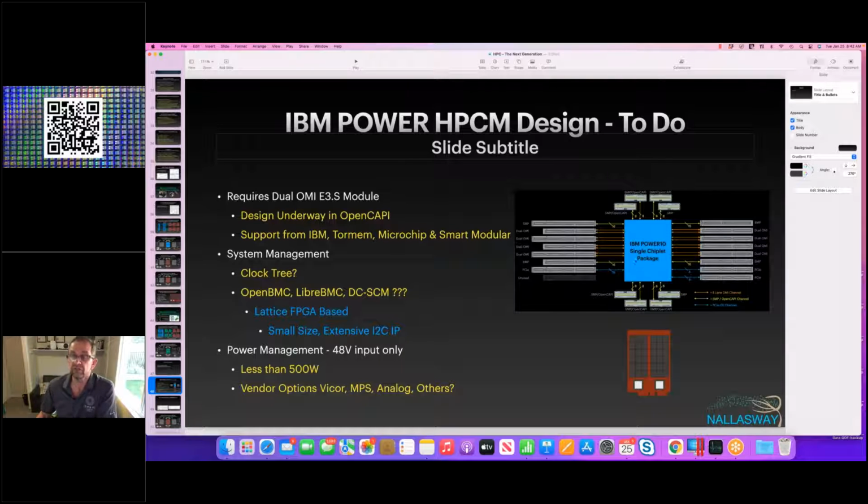Obviously, if you dropped in, let's say, an Intel CPU in here, which maybe has HBM on board and CXL, then all these channels would be CXL, and we just plug in the Samsung CXL module, and we're off to the races. So what I'm doing is, because the open memory interface is already available in a JEDEC differential DIMM format, but that's not compatible with what we're trying to do here.